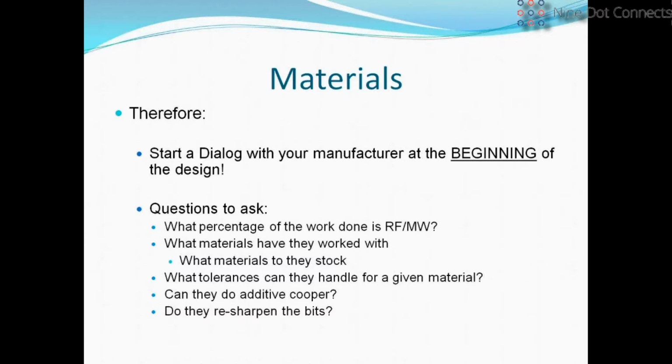However, there are companies out there. One particular company recently did a presentation on additive copper at IPC San Diego. It's a company out of Carlsbad, California called eService, and they're being very aggressive about getting their technology to manufacturers here in the United States in particular. They've perfected it. They've got additive copper working, and they were bold enough to suggest that by the end of 2015 it will be a very common practice, which is a great thing. So ask them if they're doing additive copper, because it gives you more control, especially over the tolerances of what you're working with.